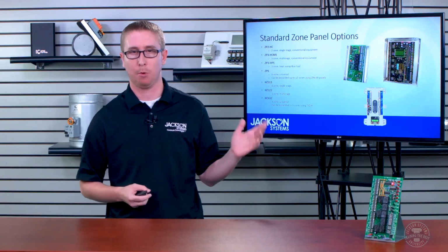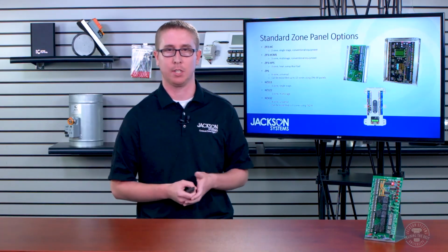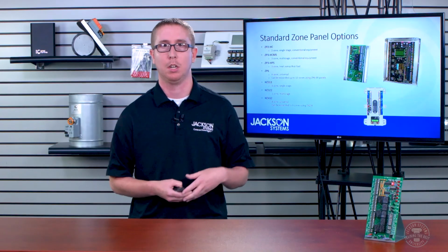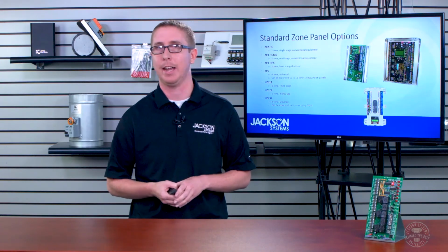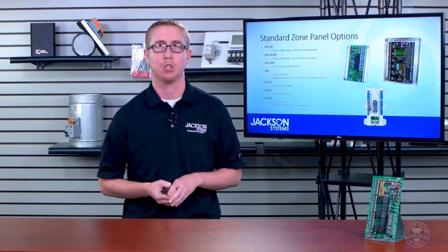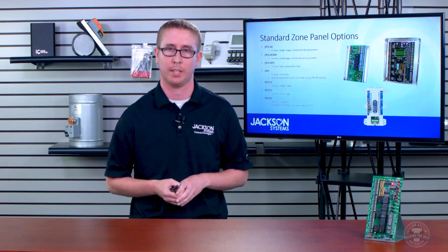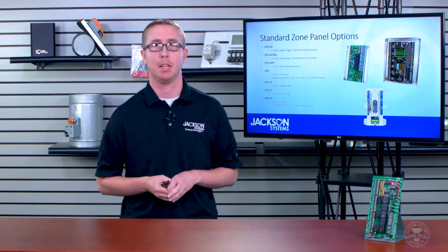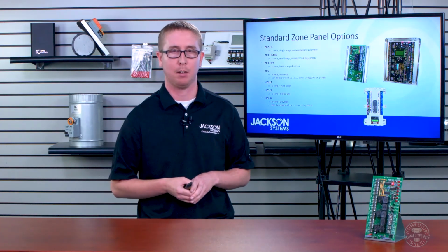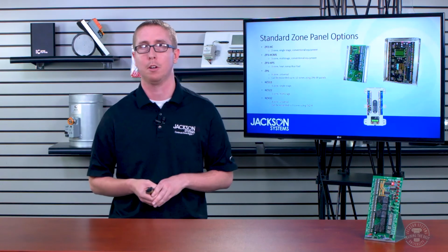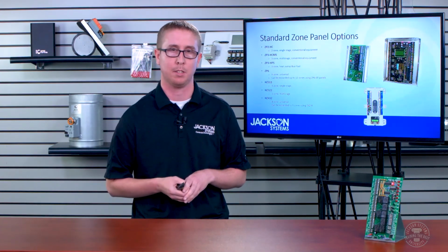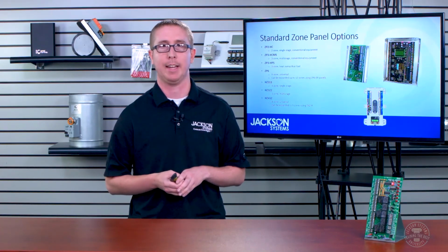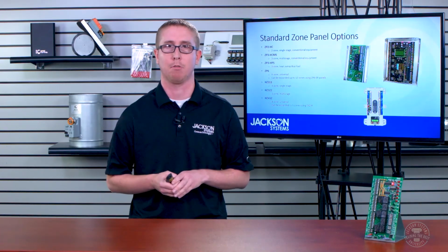Here are the options that we offer here at Jackson as far as standard zoning panels go. So there you'll see the list. There's the ZP2HC from IO Controls. That's a 2-zone, strictly single stage with conventional equipment panel. The ZP3 HCMS panel. That is a 3-zone, multi-stage compatible, but again, strictly conventional equipment. There is the ZP3 HPS. That is a 3-zone